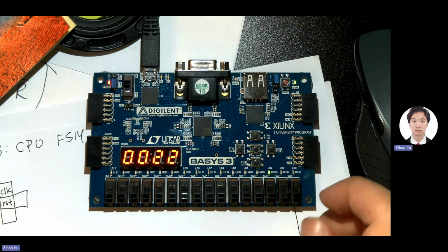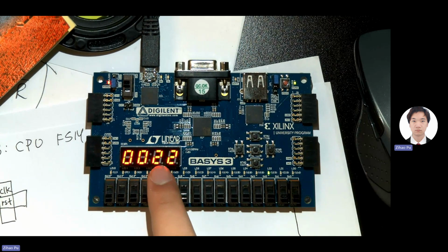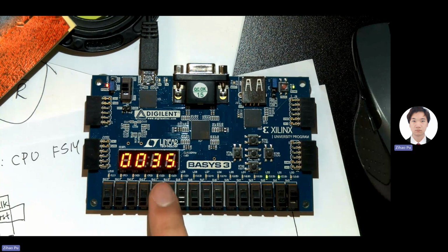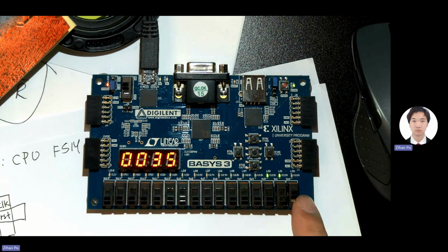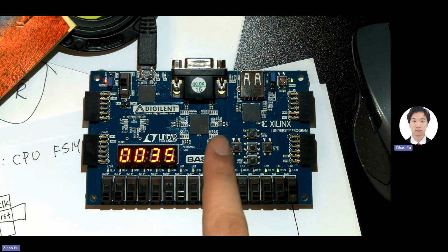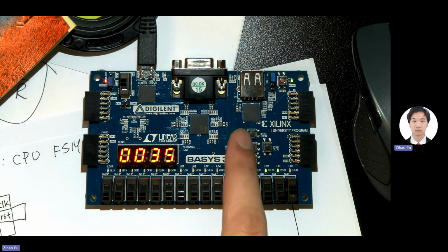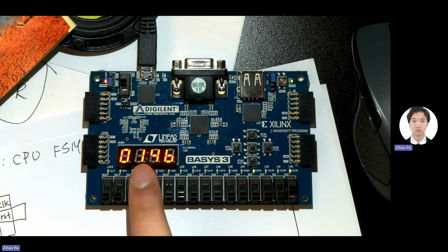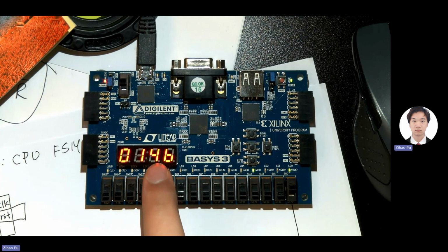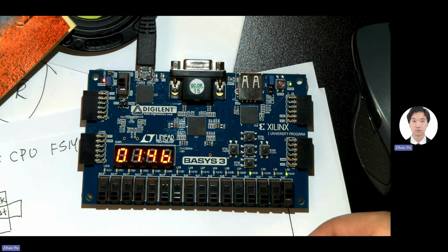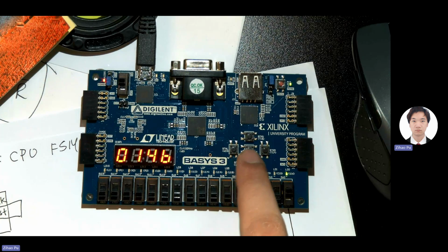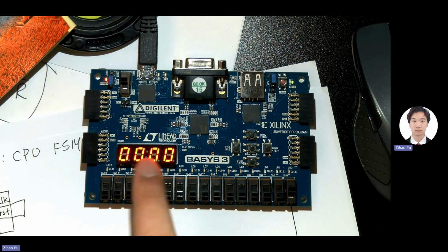Now you're in state 2, hex value is 2. And then 1, state 3, hex value 5. And then to get to S4, which is detecting 1, 0, 1, 1, is another 1. So now your match is 1, you're in state 4, and the hex value is B, which is 1, 0, 1, 1. And then this middle button takes you back to S0 and resets everything.